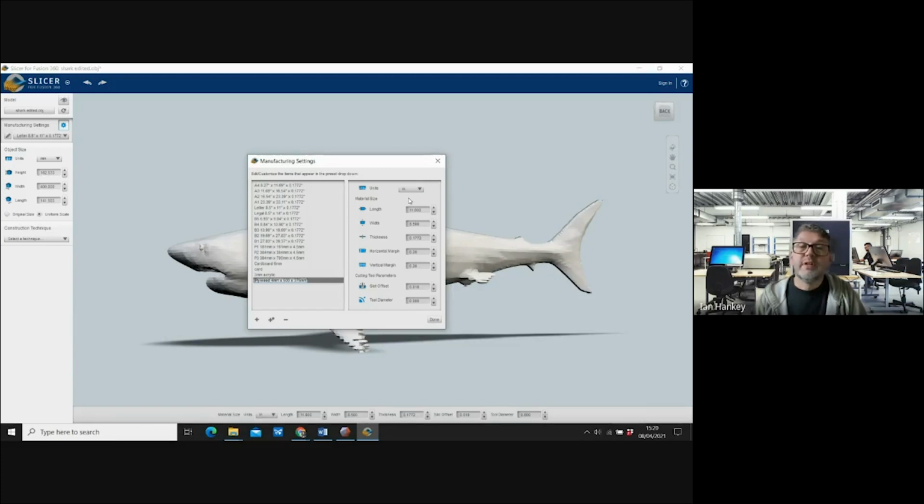So I'm going to leave it live, and where it says units, I'm going to change from inches to millimeters. And now I can see there's an automatic setting in here. The length is 279, the width is 215, and the thickness is 4.5. I'm going to change those now to suit my material. So the 279.4, I'm going to make 500.